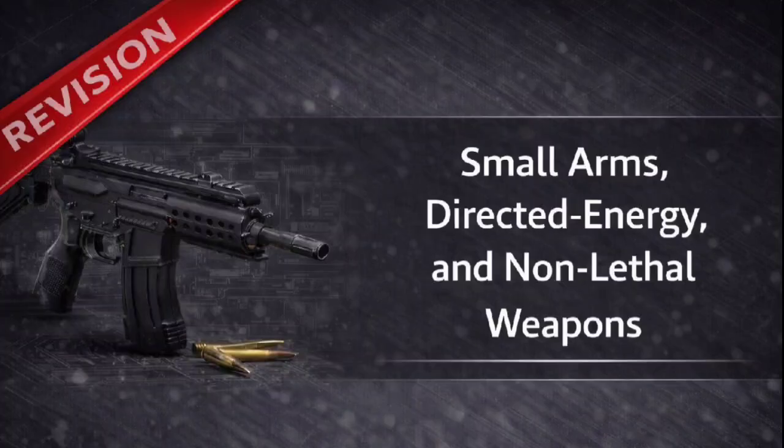The massive expansion of high-pressure gases after the bullet exits the bore. That muzzle blast can dissipate up to 40% of the total energy produced. Wow. So 0.1% versus 40%. And that huge difference in magnitude fundamentally dictates which system an engineer has to choose for a specific caliber. You can't power a machine gun with 0.1% of the energy.